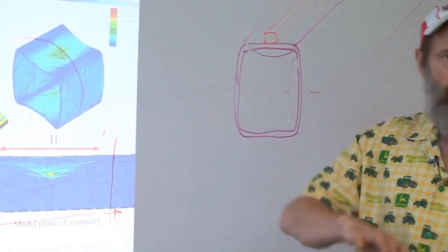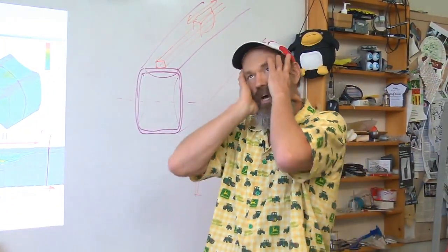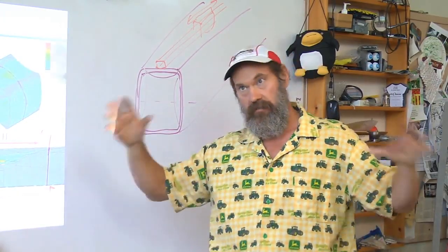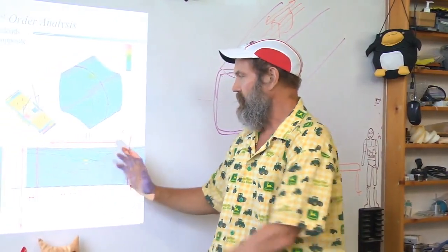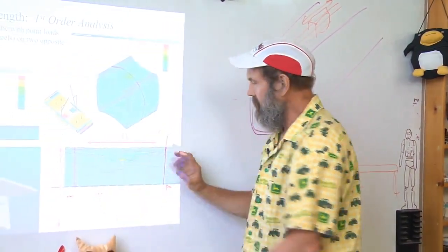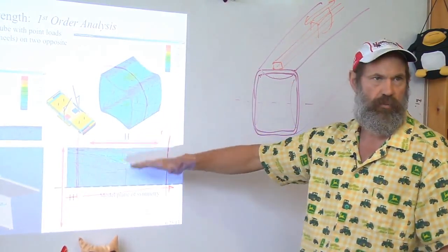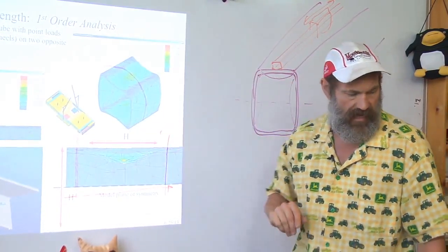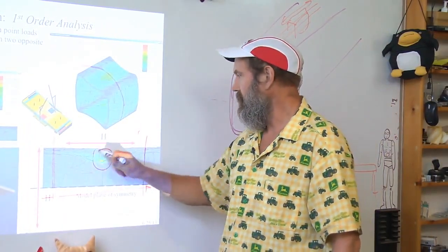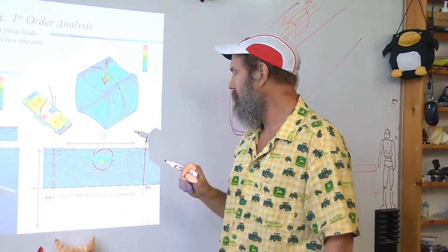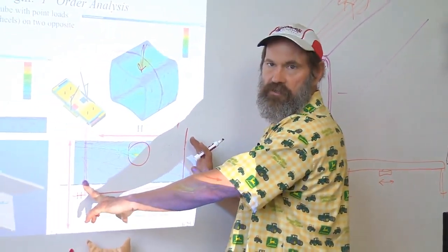So when you have a large structure and you're looking at doing the analysis of it, you can sometimes say, oh, how do I do the analysis? It's got a point load, long beam, oh! You can start to guesstimate what's going to happen just by thinking in terms of St. Venant's principle, that the material far away from here really is not doing anything to support this. Indeed, if I wanted to estimate what is this point deflection, I wouldn't even take 3 characteristic dimensions away, that is too much.